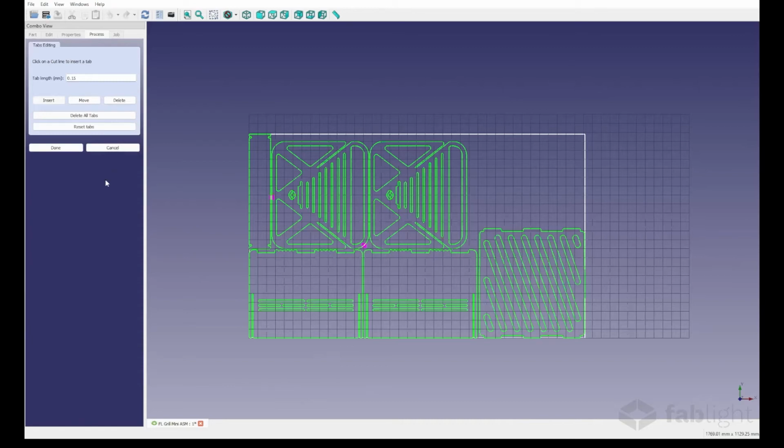The one thing I would like to say is that if something is really giving you a lot of trouble, one thing that you can do is go into your CAD software and cut relief lines in that part so that it falls apart into smaller pieces. So you can cut up those long lines into smaller lines, those big triangles into small triangles, and that way you would get less risk of tip ups and stuff like that.